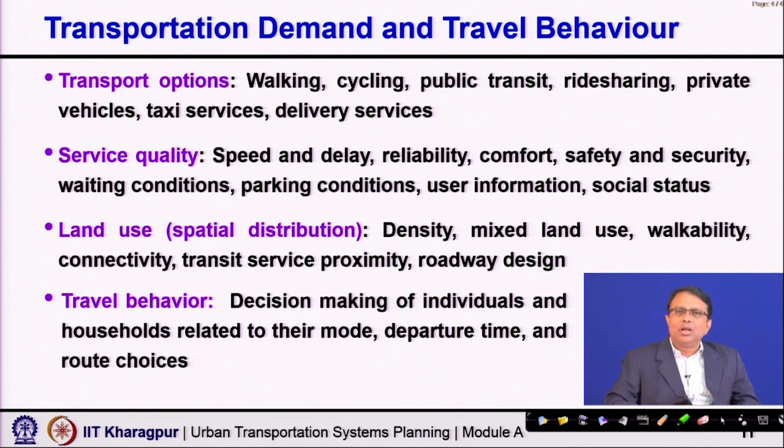Similarly, the land use. Suppose your market is located even in the next building, a kind of mixed development, then you may not be required to travel at all, right. But if the market is in one location, the residence is purely in another location, and schools are entirely in another part of the city, obviously you have to travel more. So, it depends on the density, whether it is mixed land use, the walkability, and the connectivity of that area. So, the land use and spatial distribution really influence demand.